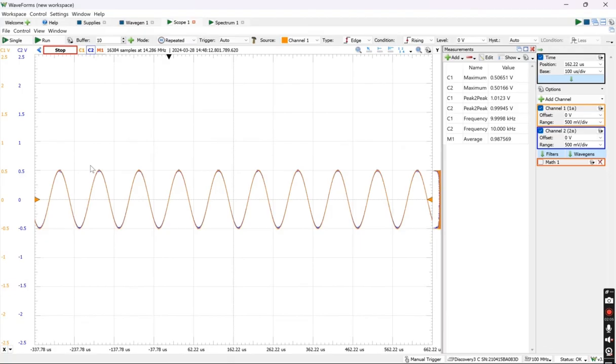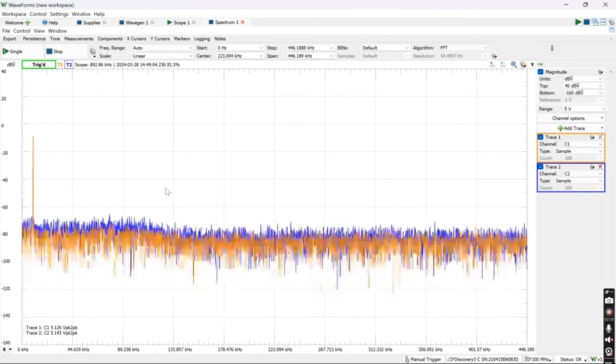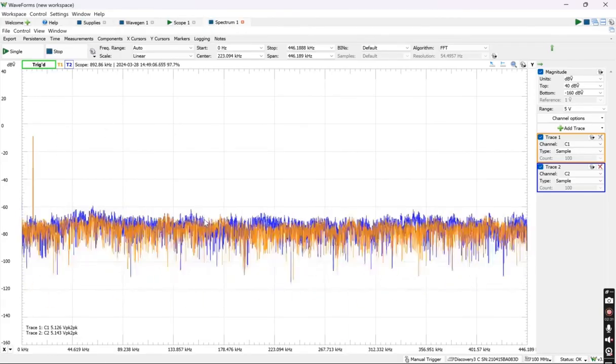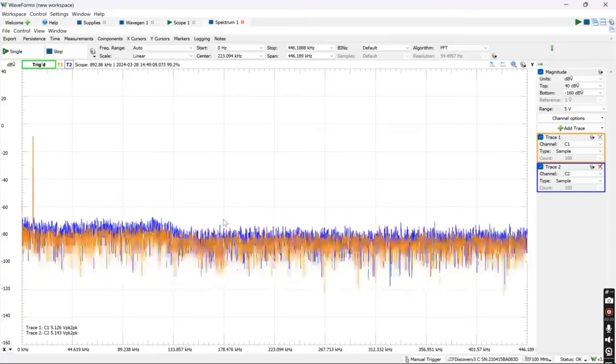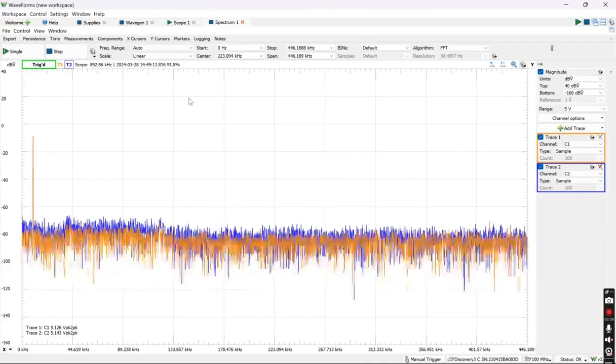So to determine the linearity of the circuit, we first noticed that the overlapping of the two graphs is present here as well as it was present in LTSpice. This overlapping does once again assume the linearity. However, the linearity can also be determined through two other methods. First, using the spectrum, we can see here in the spectrum analyzer that the signal strength for both input and output voltages are relatively the same, which expresses linearity.